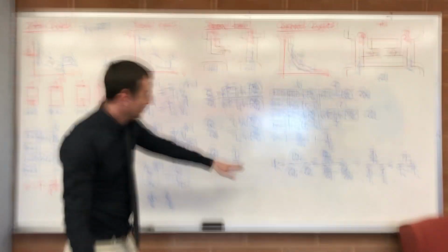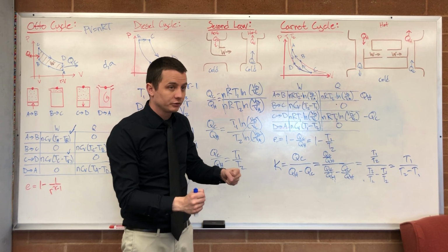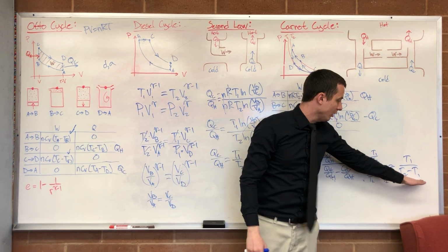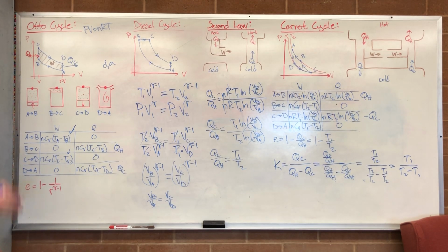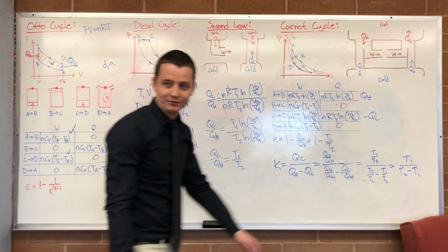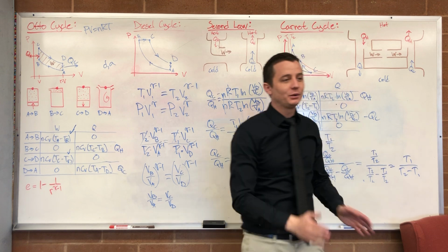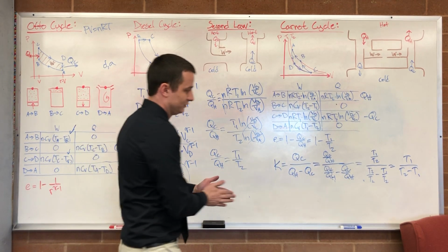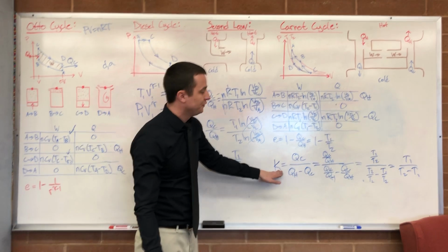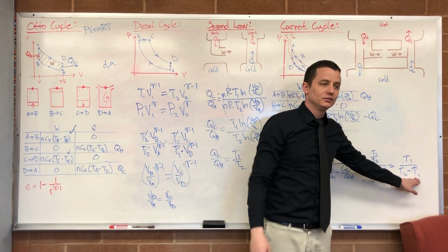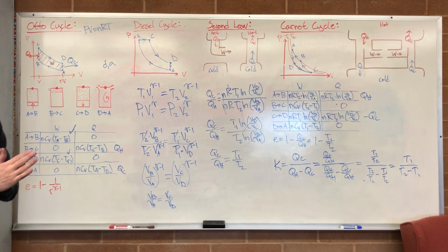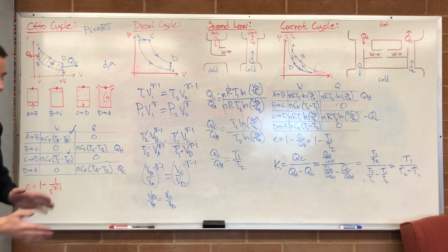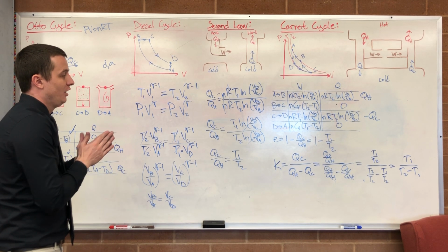And so, the max heat flow we can get from a cold source to a hot source per unit of energy happens when our hot source and our cold source are the same temperature. As long as your hot source and your cold source are the same temperature, it's real easy to make the heat flow between them, is what that tells us. Surprise, surprise, that's not effective at all, right? No. But the max efficiency we can get depends on the temperatures, is all it's saying. Okay, I see. So you can't achieve a perfect efficiency with a refrigerator unless they're the exact same temperature. It's kind of fun. Okay.